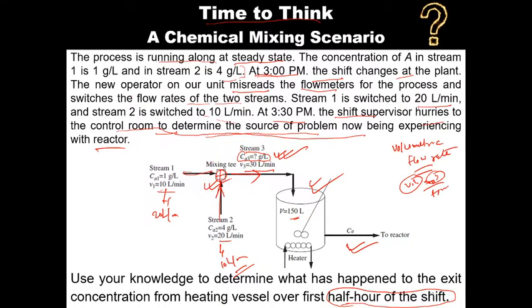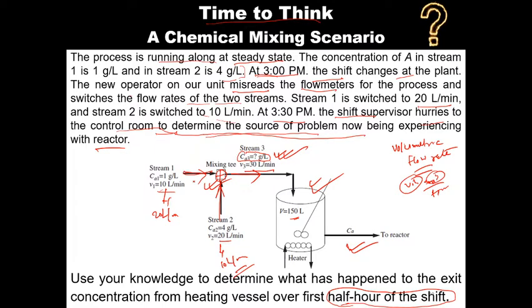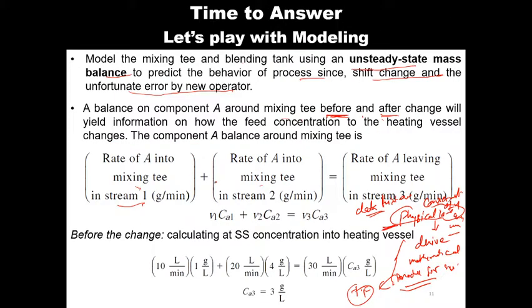Yes, sir. The rate of the concentration that will come from this side plus this side equals the third side. Okay, so based on this we have calculated the rate. This is the volumetric flow rate and this is the concentration of the first stream, we just multiplied. We have calculated this rate of A and the rate of the second stream 2, which equals the third, right? V1, V2, V3, CA1, CA2 are already given. Based on that, you can calculate the CA3. Am I right? Any problem?